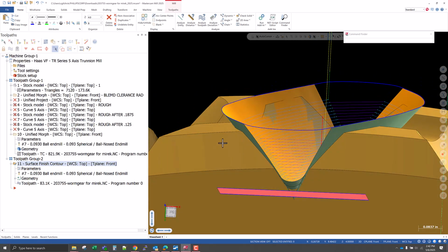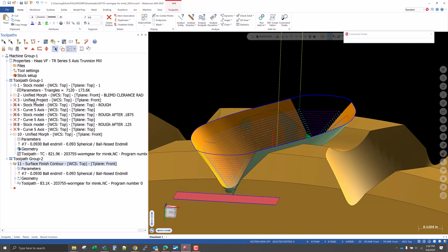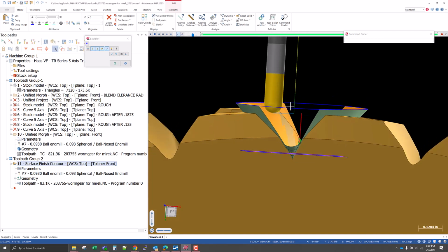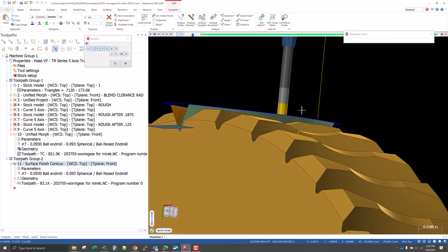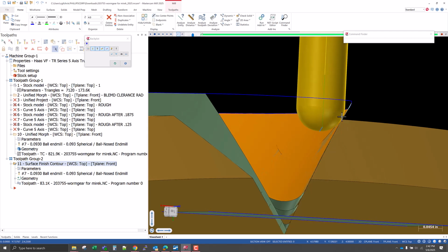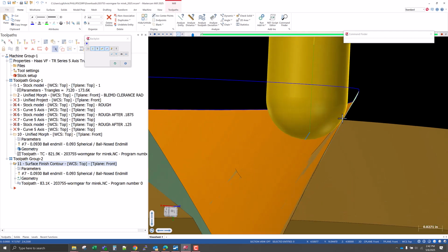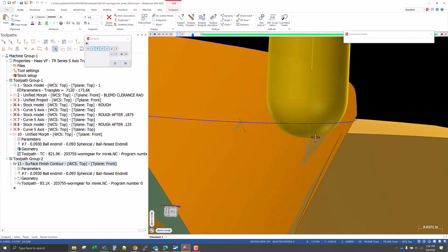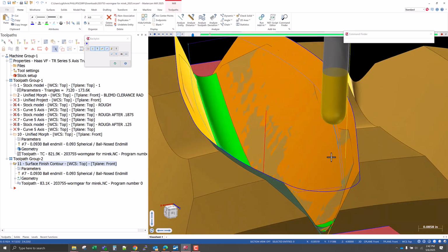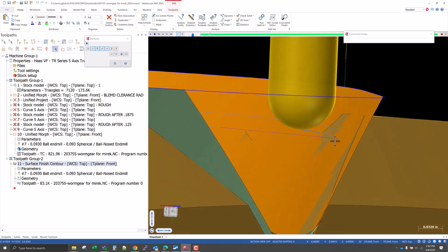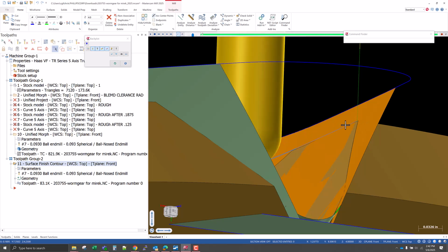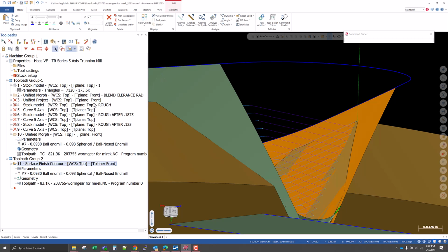So now I've used that cut depths to eliminate the first set of top passes by telling it, go ahead and start 50 thousandths deeper. And it looks like that's probably pretty good for contact. That first pass, nice right there on the tangent of the ball. So that's probably a good starting depth. If it's still too high, I can push it deeper. And we know, let me just align it so that that pass is right at the top edge visually. So we know that's where it was, right?